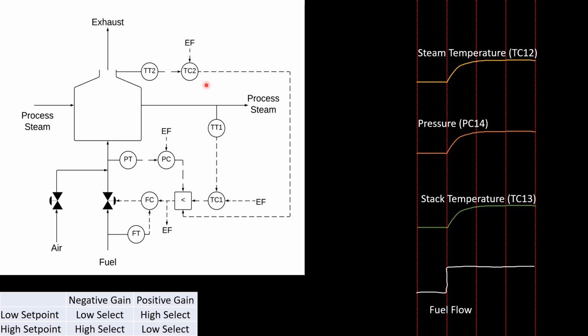If fuel pressure is too high, then a stable flame might not be sustained within the heater. And if too high of a stack or tube temperature occurs within this heater, then the internals of the heater can be damaged. Therefore, high set point override controllers for both stack temperature here and fuel pressure here must be implemented.